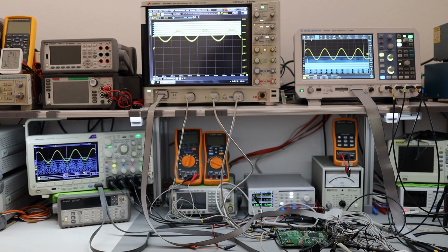Parallel bus is pretty basic. There will not be much going on in there. We'll be using our demonstration board which has an FPGA to generate a parallel bus signal, and this parallel bus is connected to a DAC. You can see on your screen all three oscilloscopes are measuring the parallel bus using a digital channel and measuring the analog output of the DAC. So we have three different classes of instrument to cover the whole range of operation.